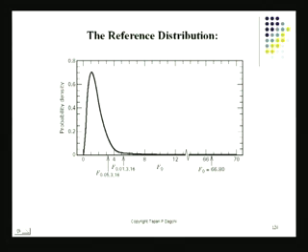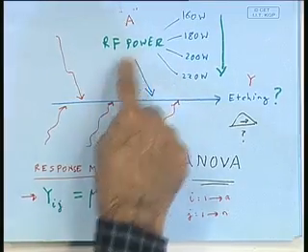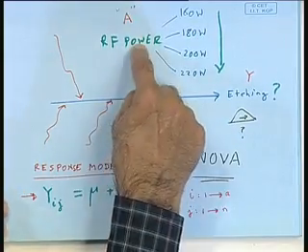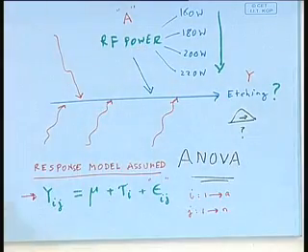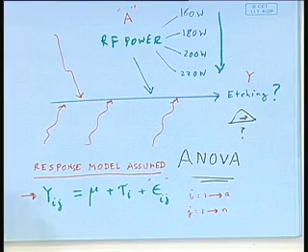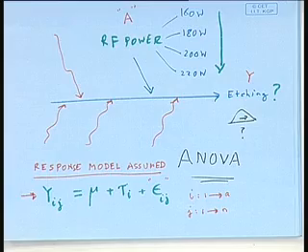I should again go back a little bit and tell you that such results are not possible to be obtained even at this time using only theory. Theory cannot tell us this. We have some empirical models that can tell us this. But if we come up with a new process and we've got new factors involved, as far as process factors are concerned, as far as noise factors are concerned, you end up with some new factor there, which will be true for any new R&D process. If you do ANOVA and an F test, you'll be able to say with some confidence that yes, changing a particular design factor or a process factor has a significant effect on the output.